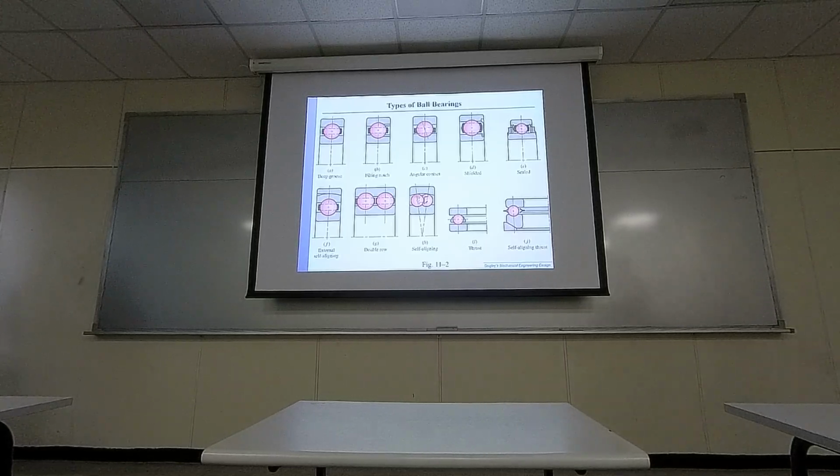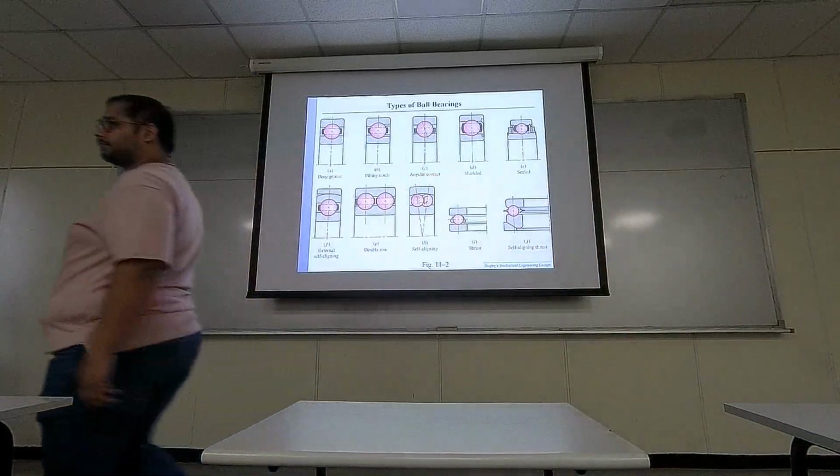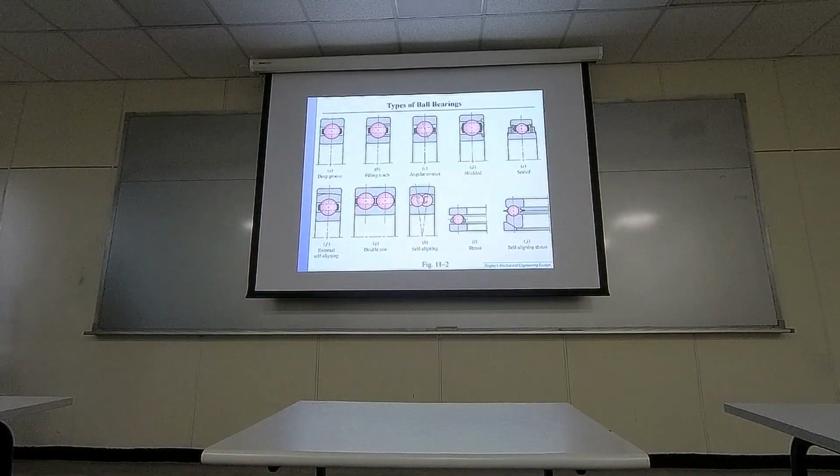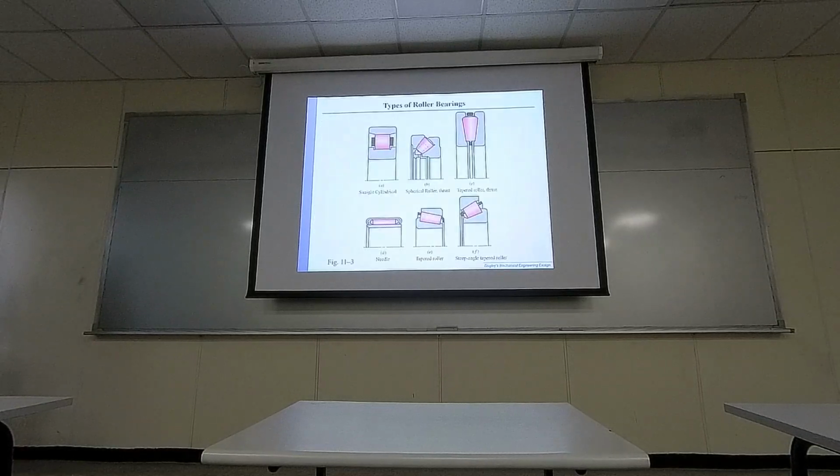So it really depends on the choices of bearings, and of course depends on some experience. But in this course, we particularly will teach you how to make proper calculations for the selection of bearings. Okay. From here you can also see not only do we have ball bearings, we have roller bearings. Okay, and roller bearings usually can carry greater loads.